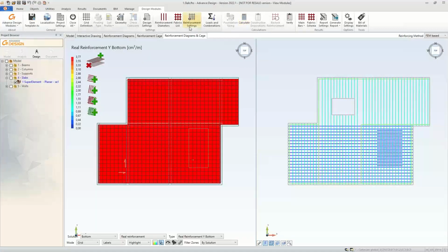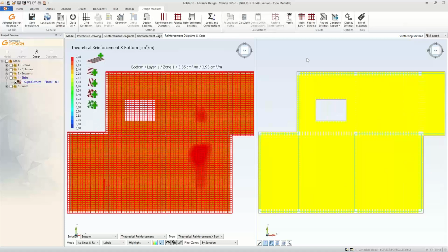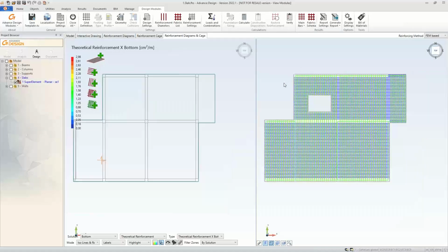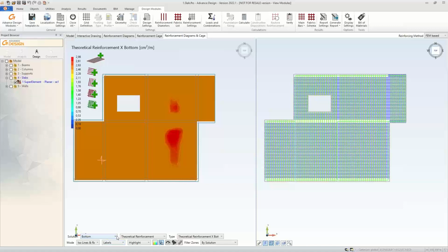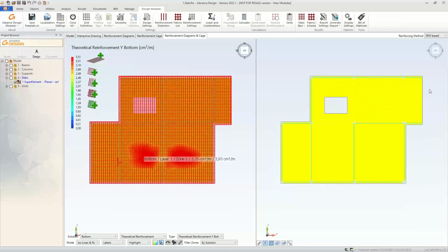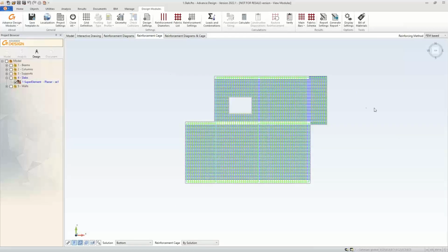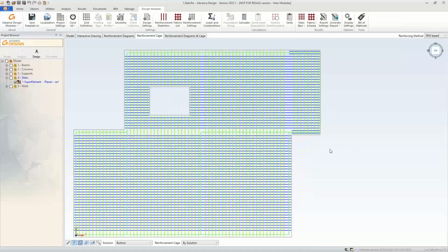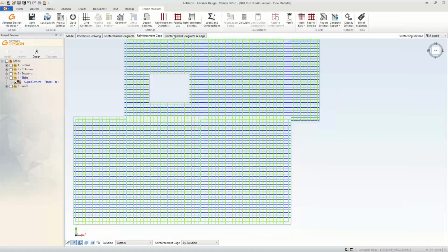When I select that option and press the calculate button, the remaining reinforcement areas, or the areas defined by me manually, will be erased, and the reinforcement is generated automatically. So we can see the bottom X and bottom Y direction reinforcement areas and values. Maybe I will show that dialog better. That's the reinforcement generated. One comment on why we see empty lines: it's because of the settings.